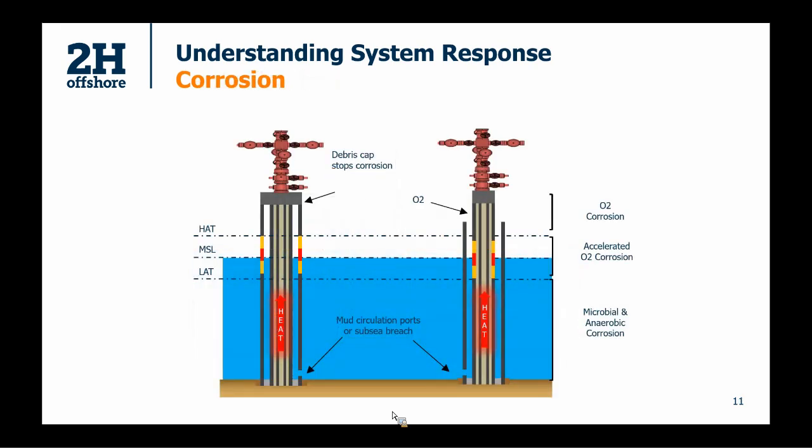So another thing that we're often worried about for conductors is corrosion. And unfortunately for conductors, the areas where we're going to see the highest corrosion is also the same area where the conductor is going to see the highest loads. It's quite an onerous situation for the conductor.